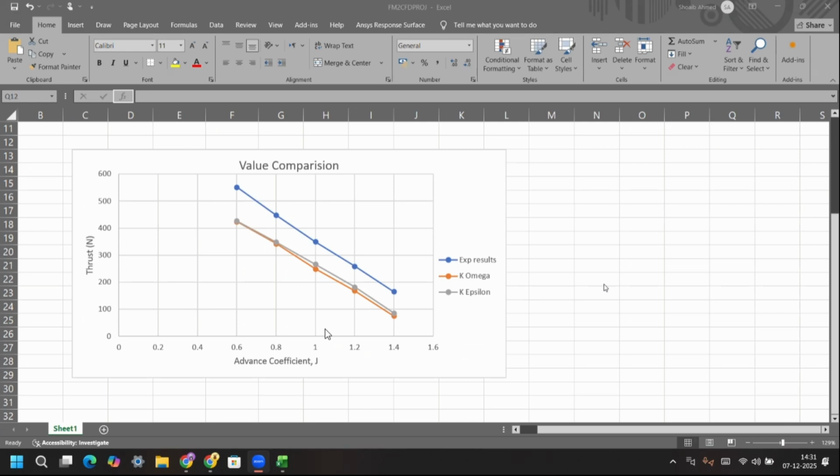Our results plotting was fairly straightforward. By setting up a parameter that would monitor the thrust on the wall faces of the propeller within Fluent, the console after every convergence would print out the value of thrust on that blade passage, and after multiplying by 5, we would get the thrust we can expect from all 5 blades working together. This was then compared against the experimental results of the Potsdam propeller test case, for which over 20 other universities and companies around the world have done CFD and EFD data. For our analytical comparison purposes, we are comparing with the experimental data.